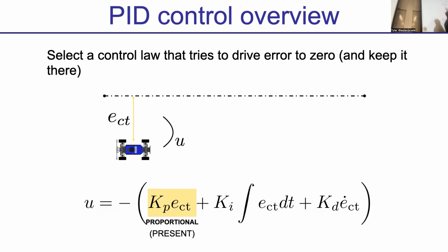Okay. And in particular, notice that there's this minus sign here. So what this captures is, if I'm below where I want to be, I'm going to exert control effort in the other direction to push my system back up and go where I want to be. Okay, so again, the proportional error captures what I want to do here. And the bigger I make this gain, the harder I'm going to try to push my system back.